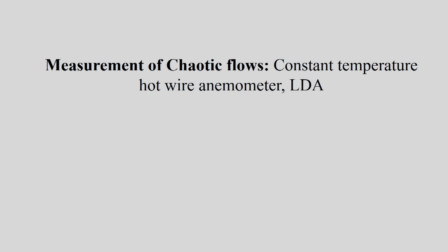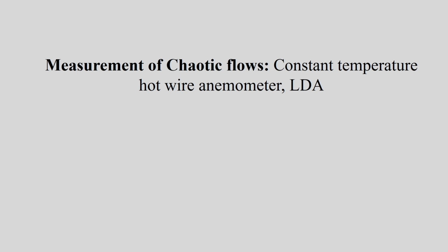Good morning. I welcome you to this session of experimental methods in fluid mechanics, and today we will discuss the measurement techniques which are used for chaotic flows. That means the techniques which are used to measure flow parameters for chaotic flows. While we discuss the measurement techniques typically used to measure flow parameters in a chaotic flow environment, we will be focusing our discussion on the constant temperature hot wire anemometer and the LDA.